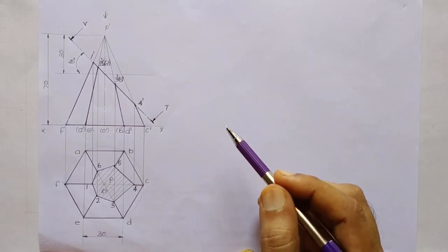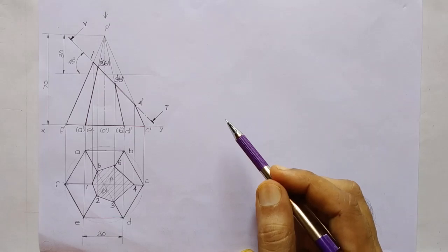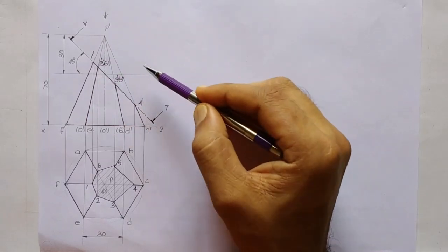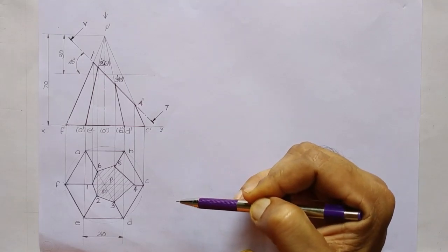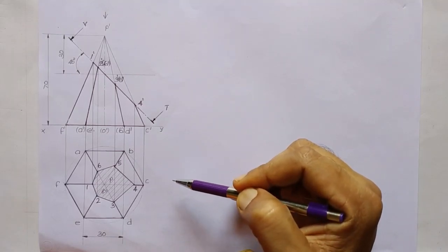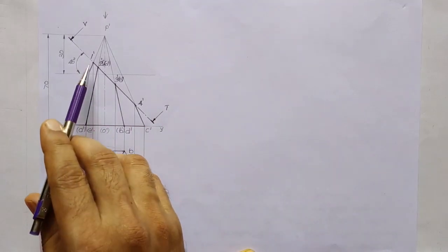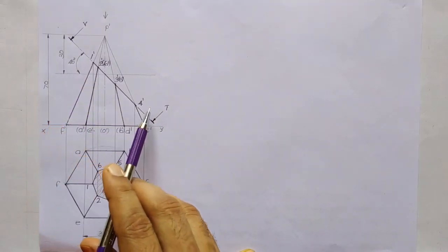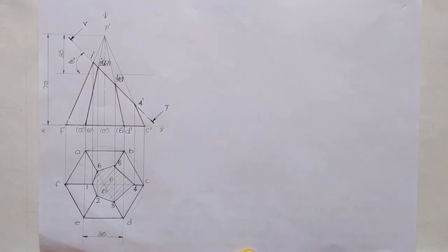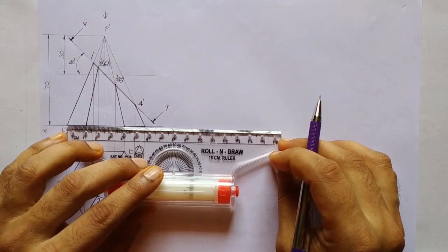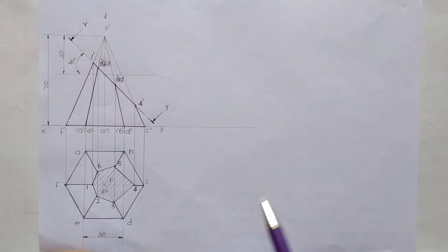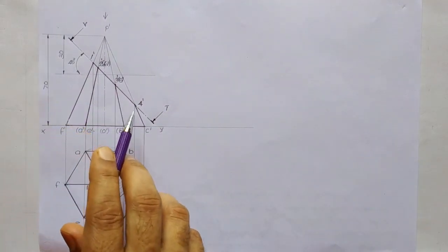In order to get the true shape, we have to observe this region perpendicular to the section plane. Only then will we get a true shape when observing the solid. To facilitate that, we will straighten this region 1' 4' and draw it on the right hand side. We shall extend the XY line slightly to the right hand side. We shall measure the distance 1' 4'.